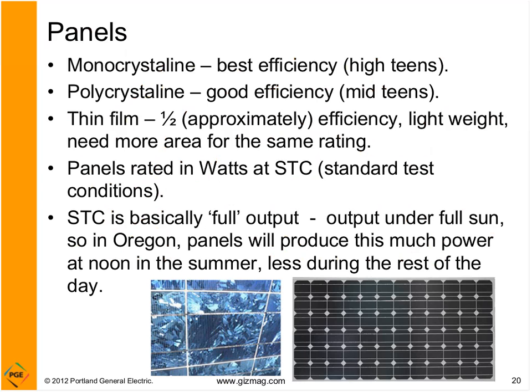Now, I should mention that it's easy to tell at a glance monocrystalline from polycrystalline. You can see this panel on the right looks like a solid black panel that's made up of square chunks of silicon. This is monocrystalline. It's very uniform in color. This over here is polycrystalline. You can see it looks like kind of an ice cube. You can see the threads and filaments and various crystal arrays there.